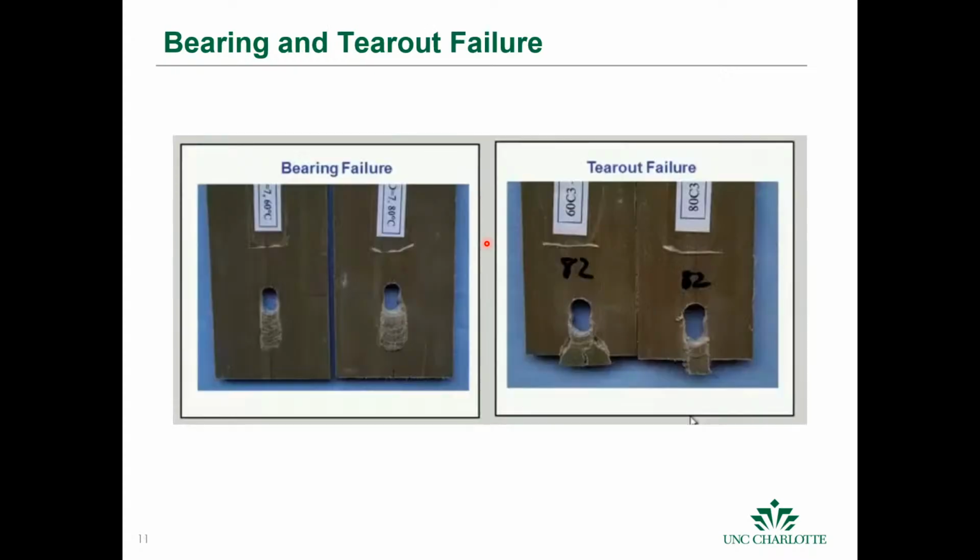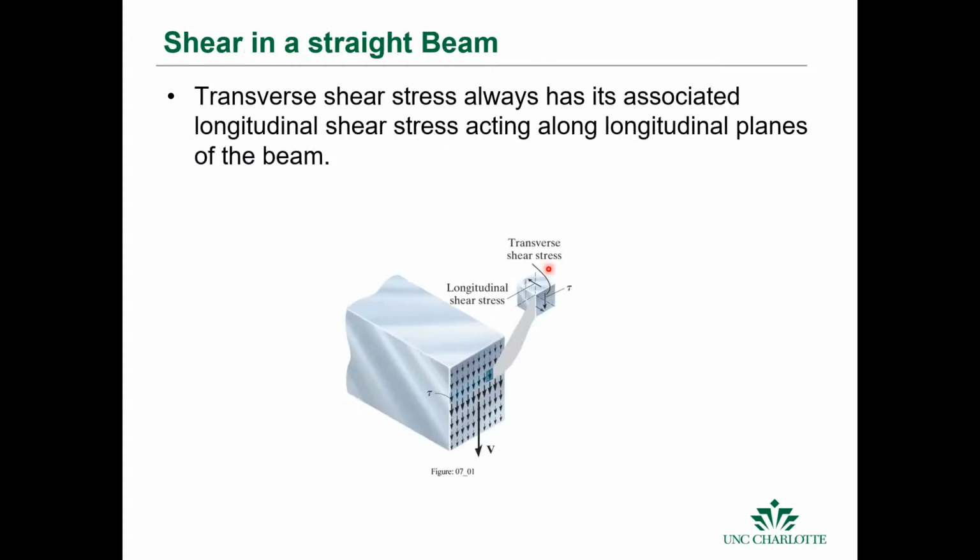So these are some pictures from the video from Dr. Norton. He shows us two different types of failure. I do believe, I don't know if these are the same material or not, but you can see in this case we have crushing or bearing failure. And then over here we actually have tear out, and you can actually see the shear plane here. So that covers a simple case of transverse shear.